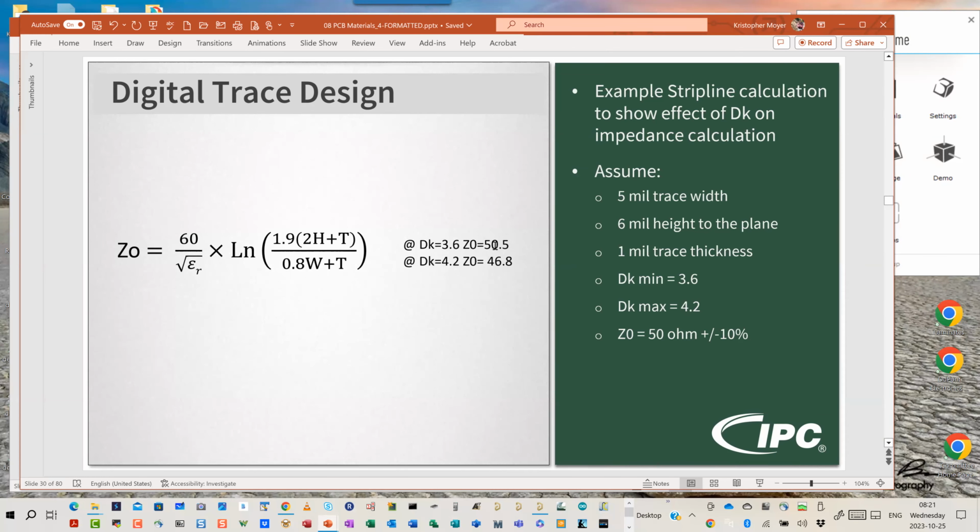If I'm building my stack up and I go in and I look and I see that the characteristic impedance that it calculated is like I had here, 50.5, I'm like, yeah, close enough, that'll work. But if it had come in something like this, I'm like, nope, I've got to change that. Okay. Does that answer your question, Mattia?